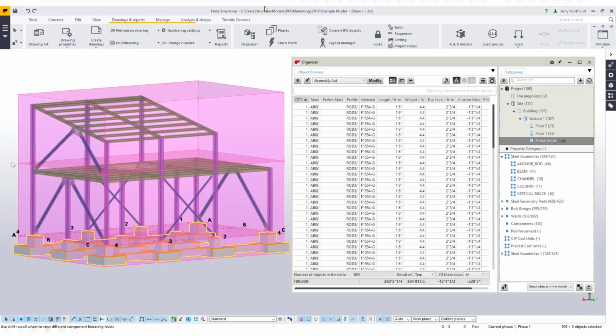In addition, I left the 3D spatial boxes that are created when I'm reviewing the spaces that I'm defining here in the organizer. So I can see that I've got this top level. Anything that's included within this top 3D space is in that volume. Likewise, for the middle space, anything that's in that volume will be included along that floor 1 line. And for the below grade, same thing. So everything that's below this, I think it's a 0 level, is included in the below grade area. And if I had any that Tekla was unsure about, or that are outside of these bounds, I would have an uncategorized label right below this as well.